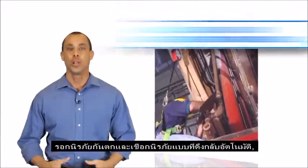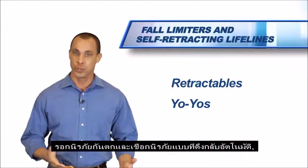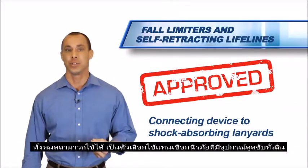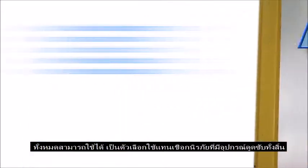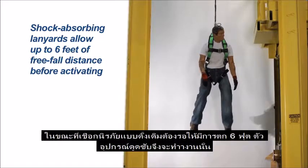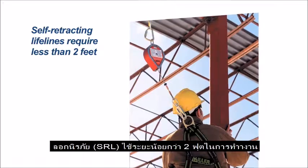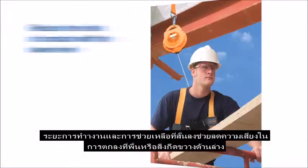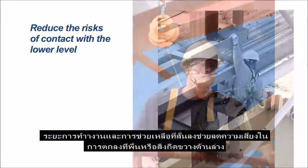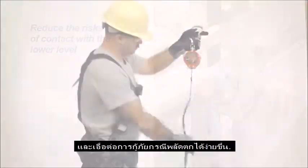Fall limiters and self-retracting lifelines, sometimes referred to as retractables, yo-yos, and seatbelts, are approved alternative connecting devices to shock-absorbing lanyards. While traditional shock-absorbing lanyards allow up to 6 feet of free fall distance before activating, self-retracting lifelines require less than 2 feet. Shorter activation and arrest distances reduce the risks of contact with the ground or lower level obstructions and allow for easier rescue in the event of a fall.